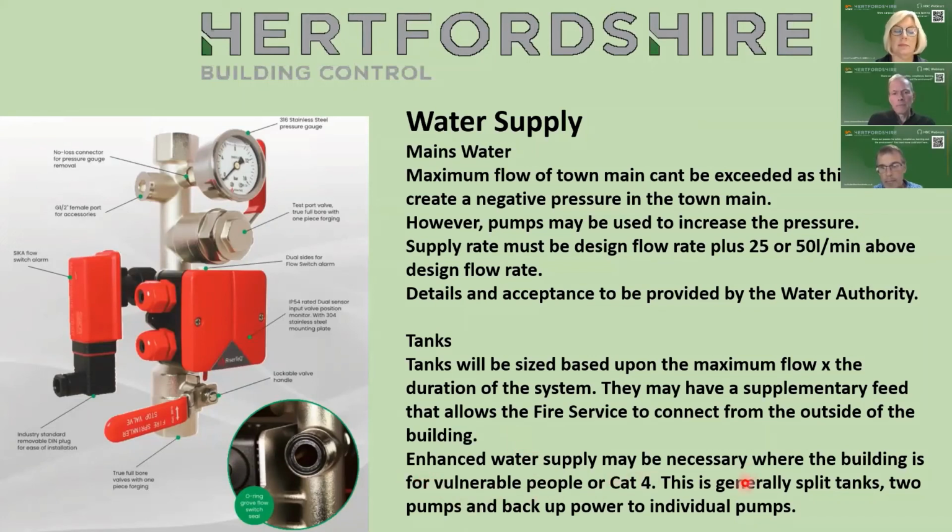Enhanced water supply may be necessary where the building is for vulnerable people or Cat 4, which is basically what we talked about, what Isabel was asking about. This is generally split tanks, 2 pumps, and backup power for the individual pumps.